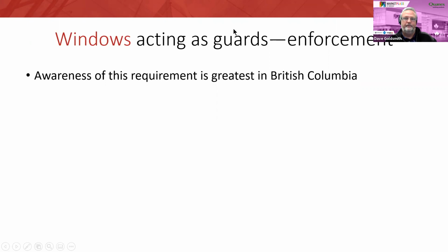Okay. Another question from Adam: can we use 3 millimeter annealed for windows that are under guard height? We have test reports that 3 millimeter annealed glass meets guard load. I'm not sure what he means by that.